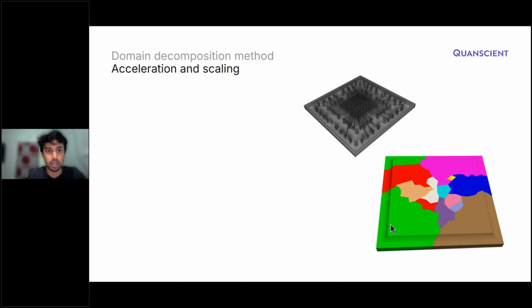It considers the partition in such a way that the number of degrees of freedom are distributed uniformly. Each subdomain is then sent to different instances of your hardware machines, and each of these is solved separately, and the information is exchanged between the adjacent subdomains. Since the large scale simulation is now broken down into smaller subdomains, it runs much faster.